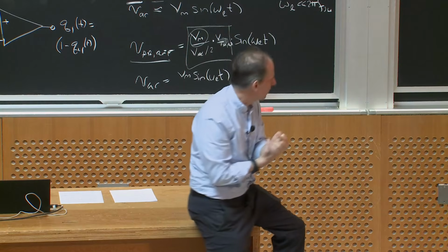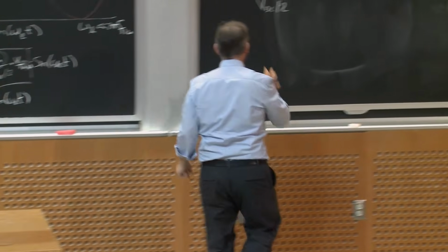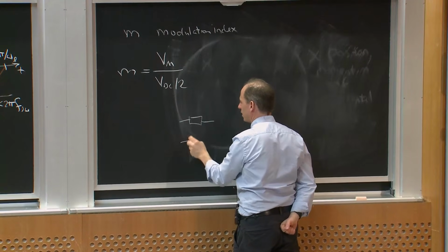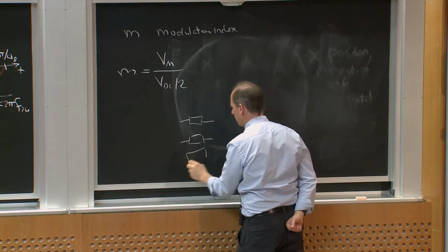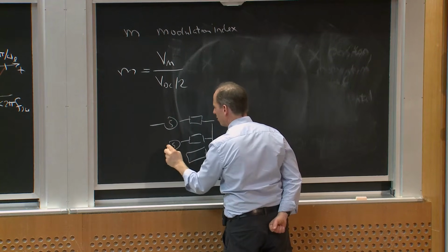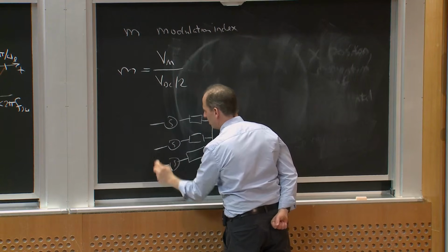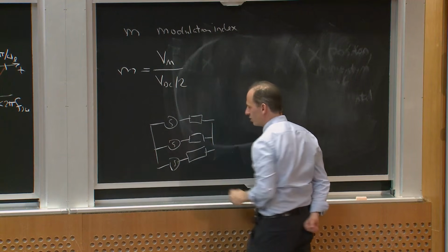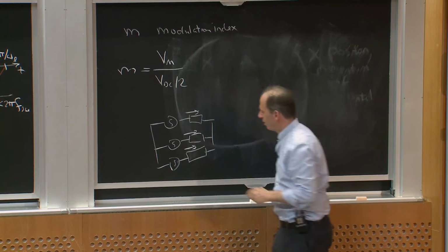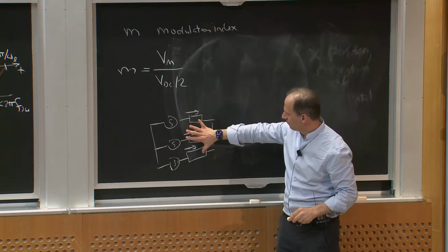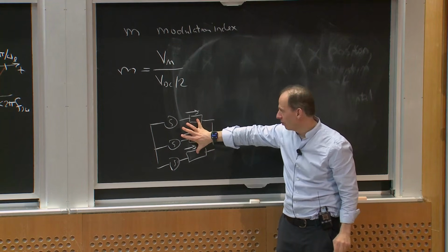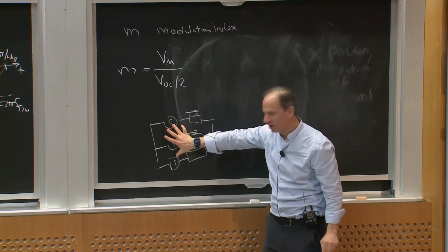So very often, the amplitude of the voltage, if I thought about some machine which is just sitting here connected like this, and maybe I'm just trying to use my inverter to generate essentially 3 voltages, which are then going to drive current into these phases. At low speeds, the back EMF voltage of the motor is low, and I want low current. I want these voltage waveforms.